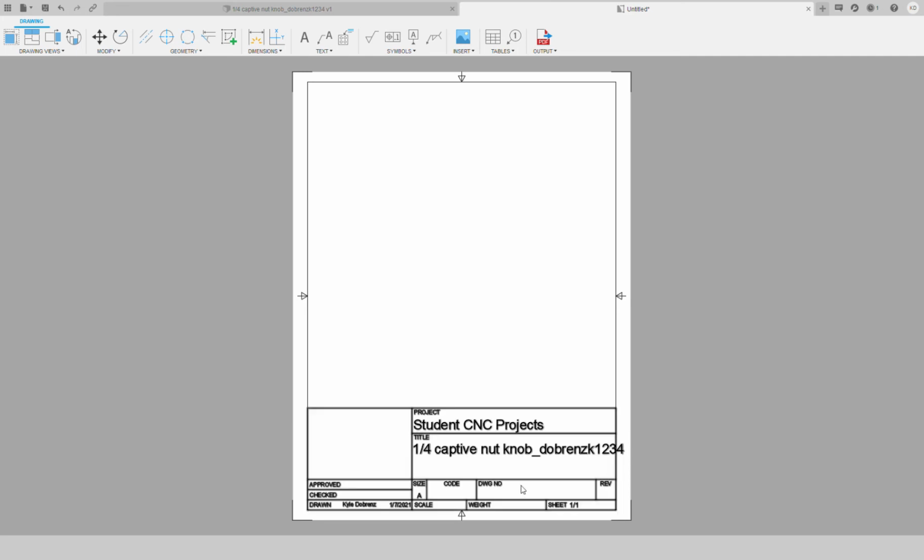These codes and DWG numbers, these are generally used when you have a very complex assembly with lots of parts, some type of a filing system to keep all your parts. REV stands for revision. A lot of times my first revision or my A revision is not my final one, where I'm going to make changes to a part to make it perfect before I reach the point where I'm satisfied and I want to print that.